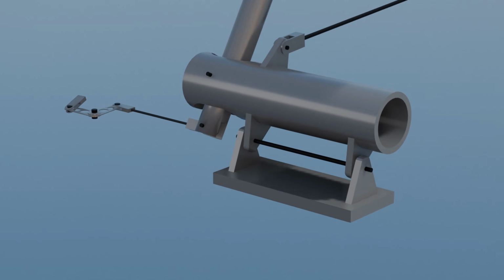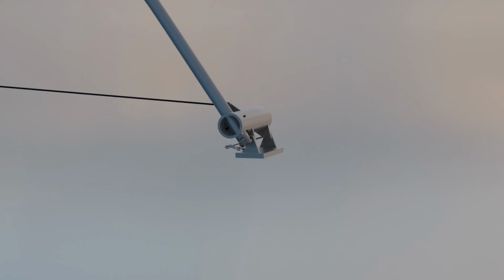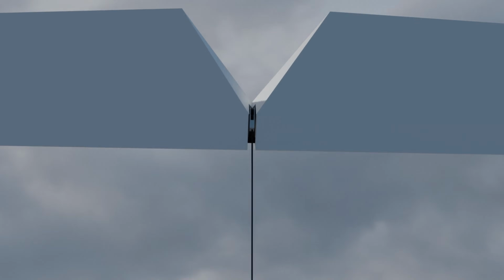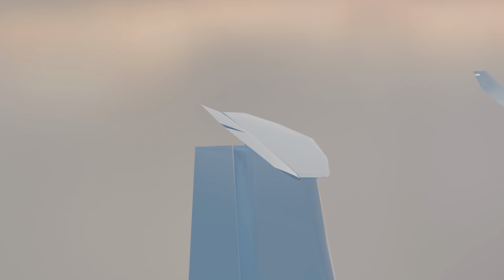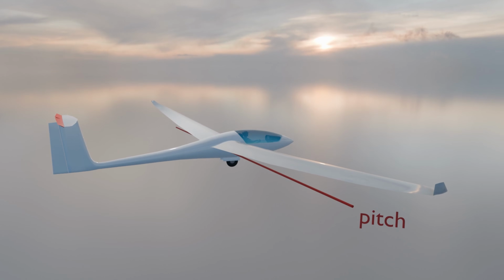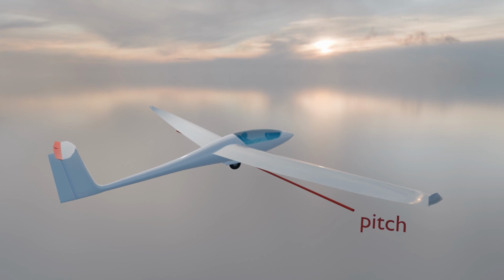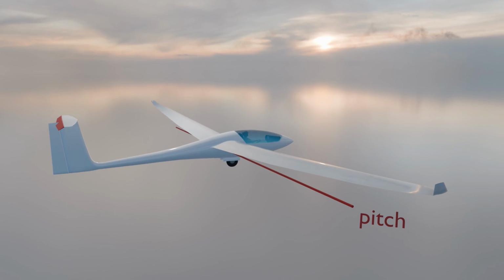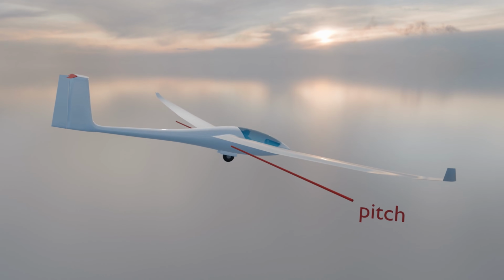The control stick is connected to the elevator through a system of rods and various bell cranks. This simple example is just meant to illustrate the hidden mechanics. In reality, we can see many varying implementations. When we pull the stick back, the control surface moves upward, creating aerodynamic drag. As a result, the tail of the aircraft moves downward, causing the plane to rotate around the lateral axis and raise the nose. Pushing the control stick forward has the opposite effect, lowering the nose into a nose-down position.